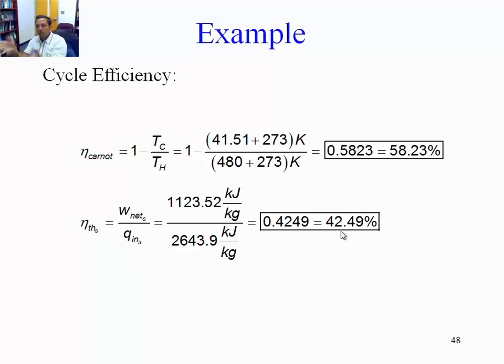Is it worth it to increase the efficiency 2 or 3%? Yes, it's huge. Because remember, you're investing 230 or more megawatts of energy from burning fuel to heat this water up in order to create mechanical power, in order to spin a generator. If you save 2% of that, you're talking about 4 or 5 megawatts of power that you'll be saving. Well, multiply that times hours, you get megawatt hours or kilowatt hours, and you can correlate that to the cost of electricity. How much is the electricity on your power bill?